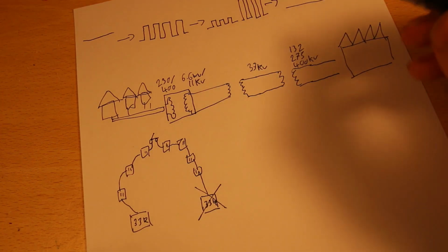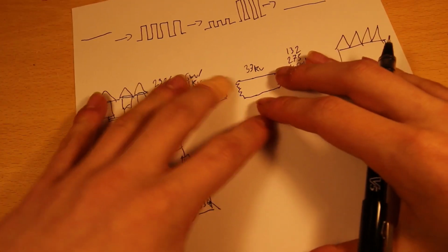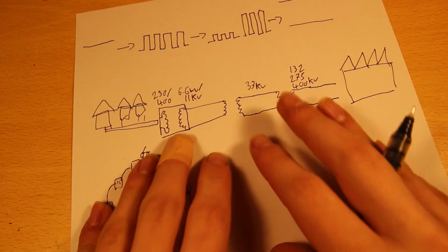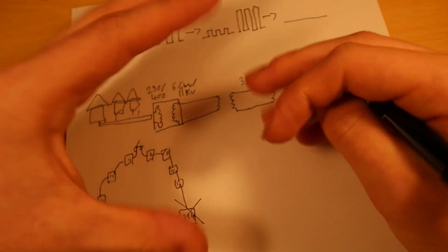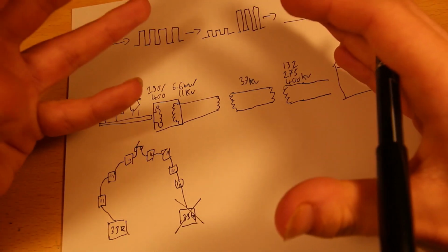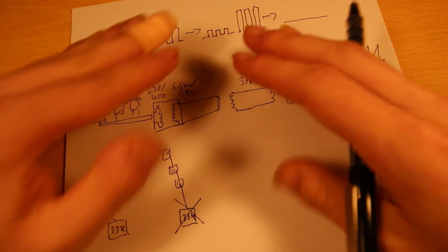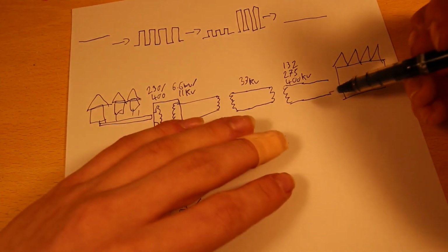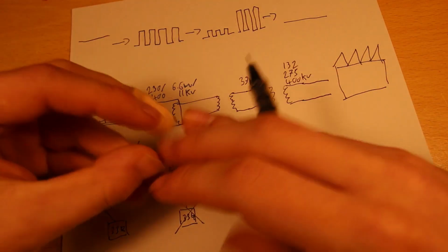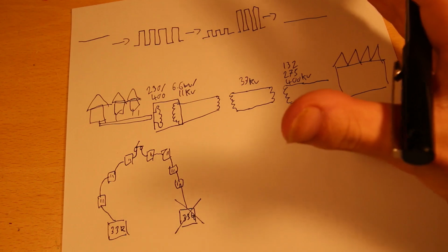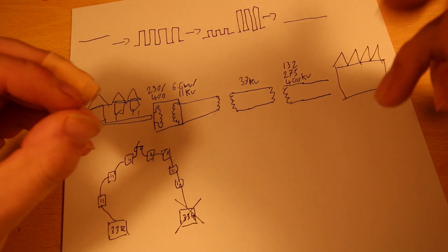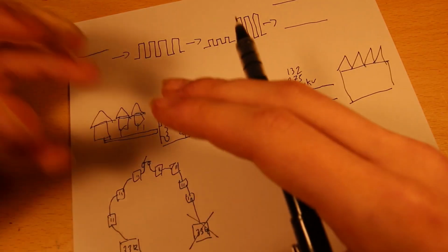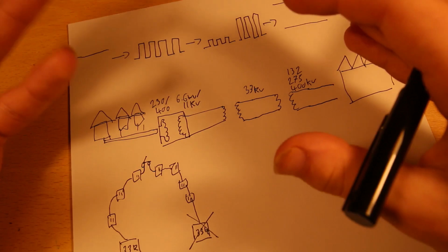The distribution like this relies, as you can see, on these voltage transformers. The reason for that is because a cable has a resistance. I talked about this last time. That resistance is usually low, but when you're talking cables on this kind of scale, where they're crossing oceans or running the entire length of countries, it could be 100 or 1,000 miles long, that resistance starts to add up a lot. And the more current you pull through a cable, the more volt drop you will get across a cable.